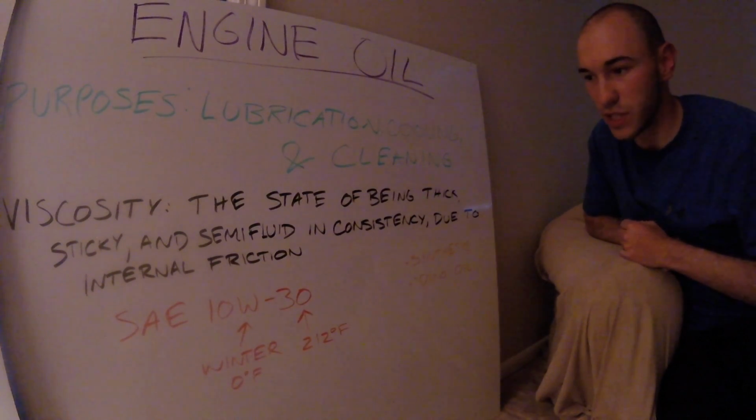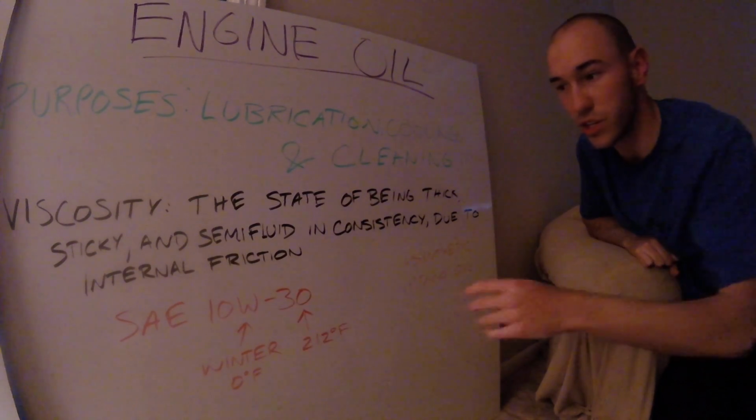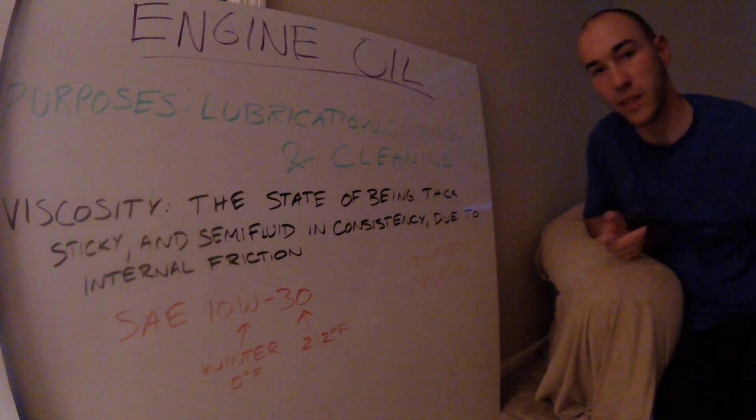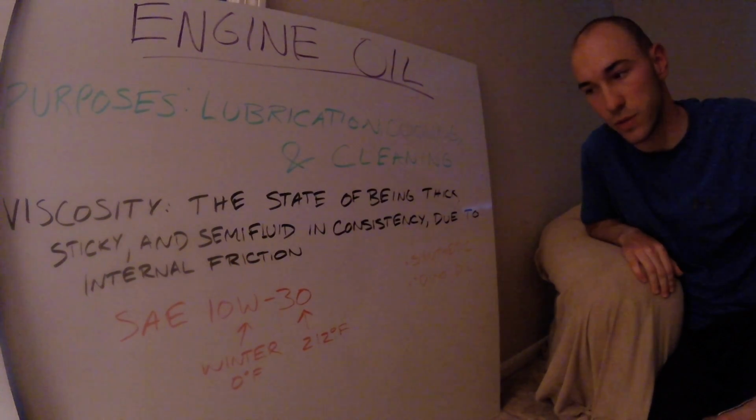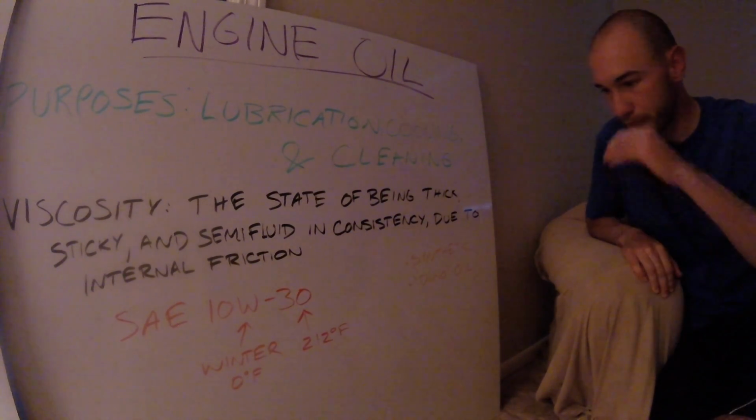Another note: if you see an oil that says just SAE 30 or SAE 20, without the W, that's a simpler oil, usually meant for simpler engines such as a chainsaw, so you're probably not going to want to put that in your car.